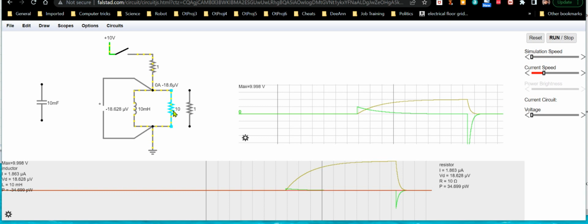You've got to buy special resistors to get high voltage ratings, and it boggles the mind, but believe me, it's true. You will blow out resistors if you try to put high voltage through them, and not blow them up necessarily, but if you put high voltage through a regular resistor, it'll arc over it and destroy it.